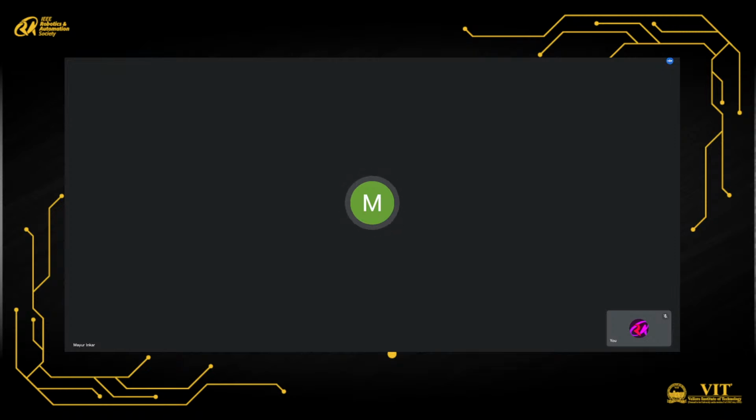Another thing about Siemens is that all their components are integrated with each other. To work with the HMI through a Siemens PLC, you just have to integrate them in the TIA Portal software, which is a 2-minute process. But with other companies, if you are using a PLC of one company and an HMI of a different company, then you have to work in a different software to program that HMI, and a different software to program that PLC, and then you have to integrate them.